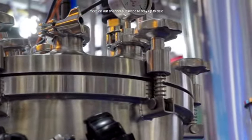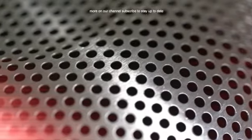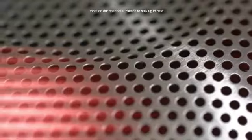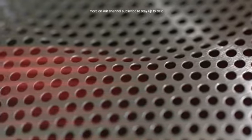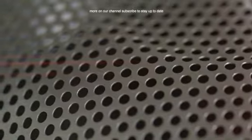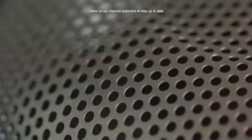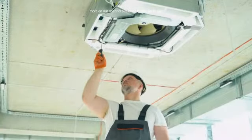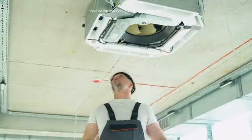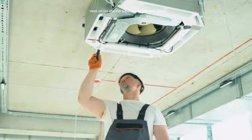Utilities like water systems, purified water, water for injection, and HVACs, heating, ventilation, and air conditioning, are integral to the facility and must be designed, installed, and maintained to prevent contamination and control environmental conditions like temperature, humidity, and air quality. For example, in a sterile manufacturing area, the HVAC system uses HEPA filters to remove particulates from the air and maintains positive air pressure to prevent unfiltered air from entering.